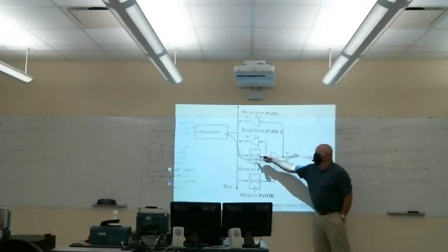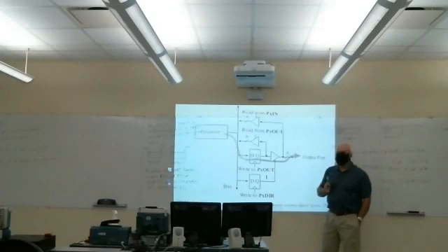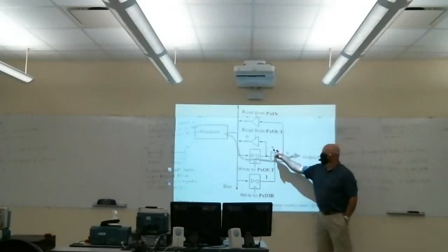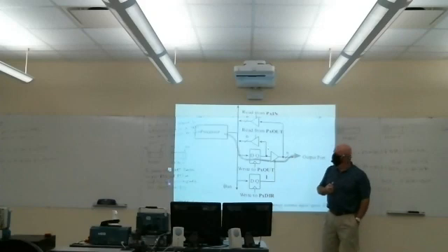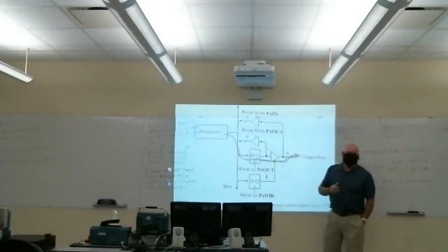But we can actually read the latch value by reading from that output register. Again, I don't think this would be a common operation, but it's essentially like reading and writing from memory. These flip-flops are essentially memory. You could use it as an additional byte of memory, I guess, but we could read from that value that's been previously written there. Or you can read directly from the output pin. If we're driving this high, we can read that by reading from the input register.